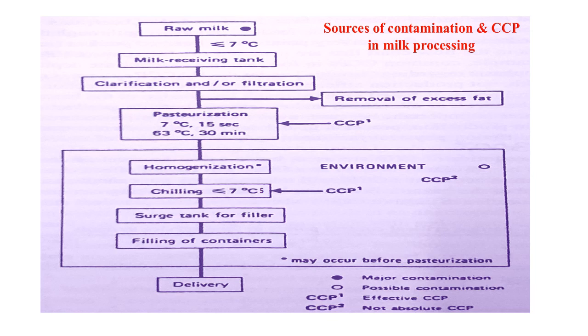So similarly, in every point of any product processing, there are certain specific points which we need to identify, and there has to be a system to monitor them, and we have to take action when there is a deviation. So time and temperature have to be monitored. When there is a change or breakdown or deviation, we have to correct it. Sometimes if it is not possible to correct immediately, we have to stop the process.